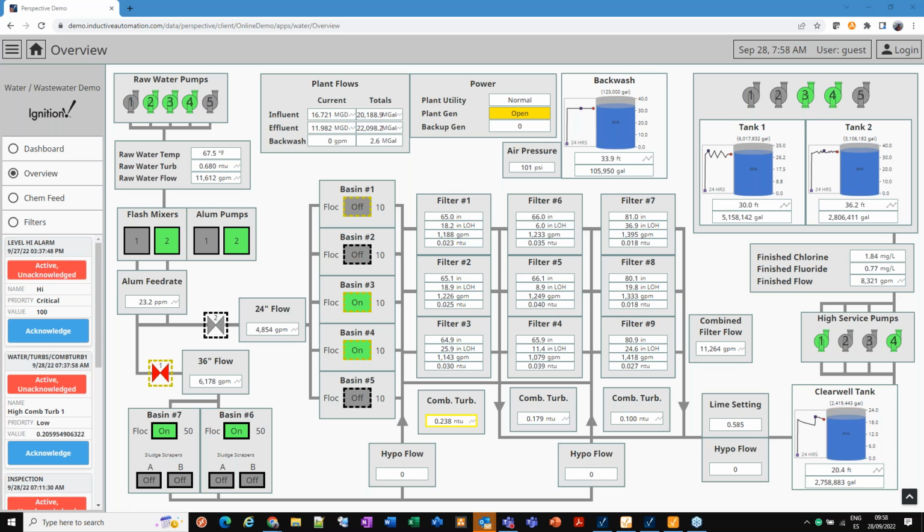I don't have the full list on hand now, but there are also drivers for Modbus TCP, etc. In some cases, where PLCs are very rare, with Kepware in between it will work with no problem. We have had no cases where it was not possible to get data from a PLC, as long as the PLC can be connected to the network.